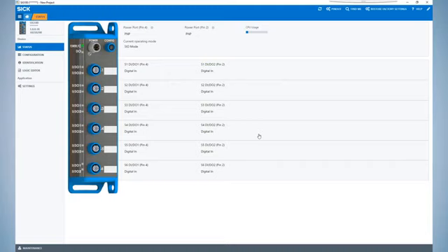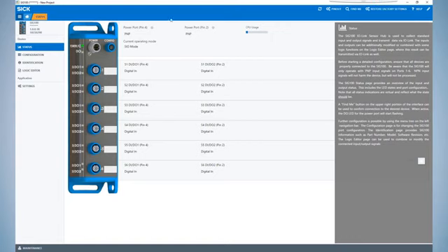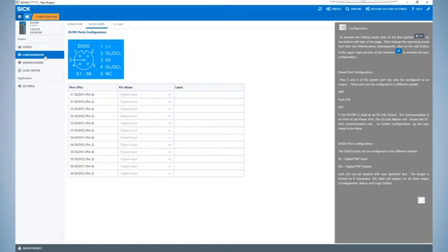Note that changing the username access to Maintenance will also allow the user to change device settings found on the configuration and logic editor pages. The Help button will toggle a help screen on the right side of the interface for each configuration page. This provides more information about the SIG100 as it relates to each page. Note that the help screen will stay open as you toggle between different configuration pages on the configuration page tree.